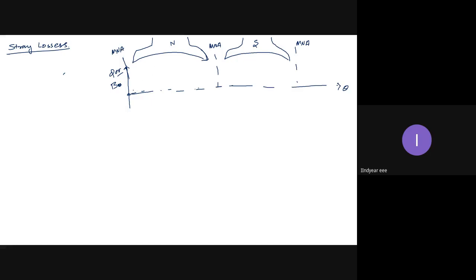When the space falls under the pole, the flux starts increasing. And observe, from almost the edge of the poles, the pole face area is constant. You can observe, let this be the armature. And if you see the pole structure, it will be like this. So at the tips, the area is a little bit more. At the center, the area is a little bit minimum.